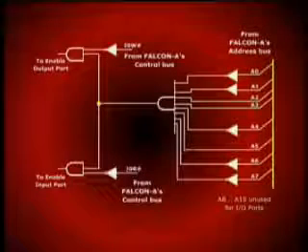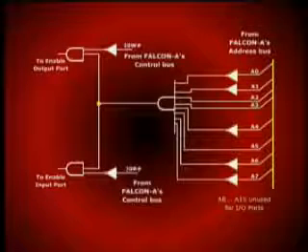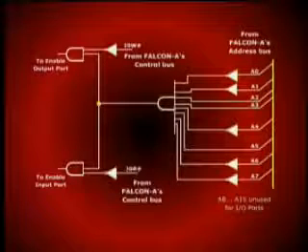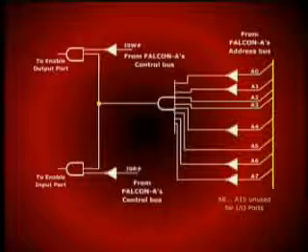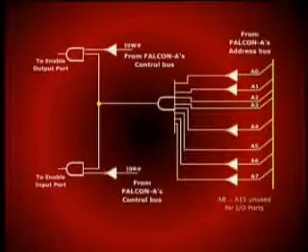The output of this AND gate enables the input port. So through this example, you could verify and see that the same address is used as an input address for one device and as an output address for the other device, but not simultaneously. At one time, it would either read data as an input from the input device, or write into the register of the output device.